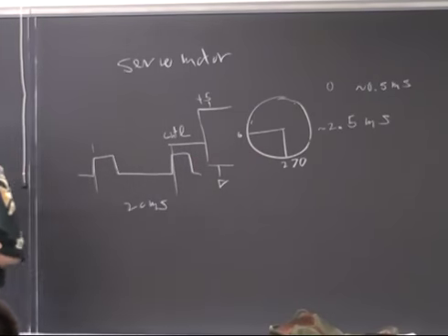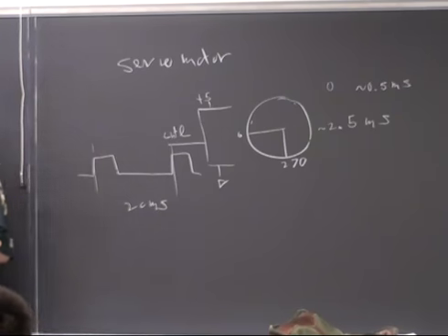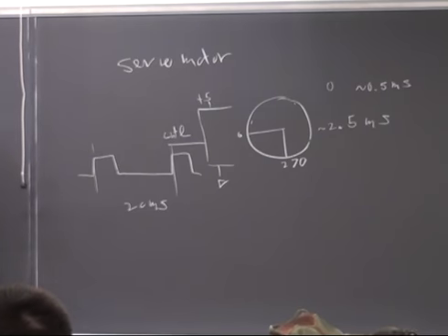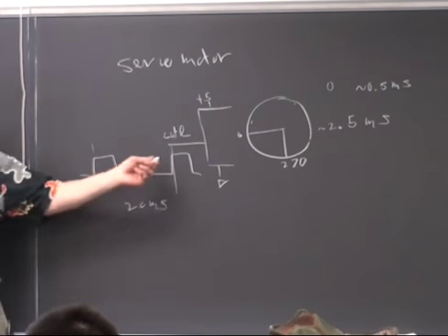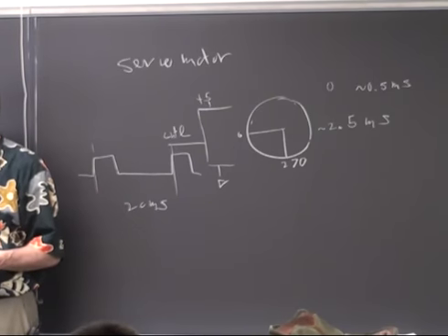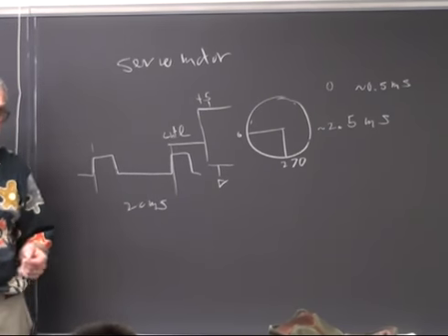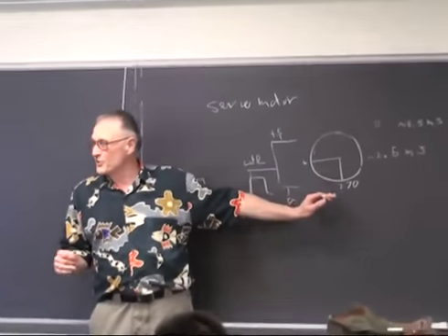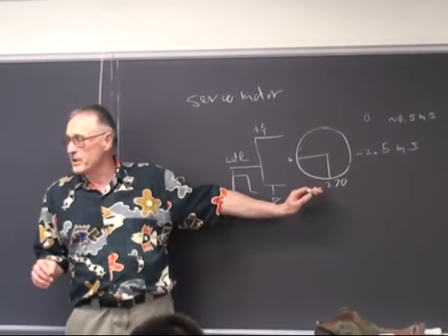Servo motors are variously, yes? I have a question. So is the difference between a servo motor and a DC motor just the electronics that are attached to it? Yeah, it turns out that inside servo motors are a small DC motor and a gear train and a feedback system. But from the outside, they become positionable by a pulse width.